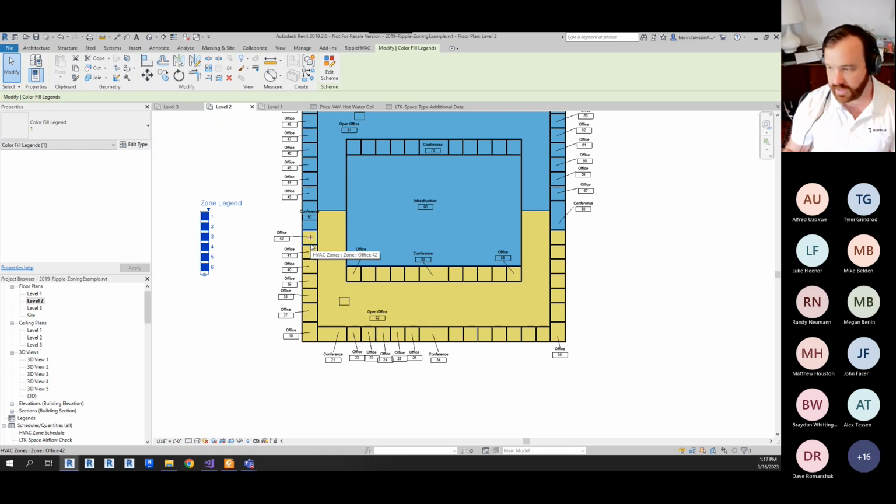So ideally, everything on the same VAV zone has an identical load profile. Throughout the day, it's getting hit exactly by the same sun. It's got the exact same people using the exact same lights, the exact same computers. Functionally, that just never happens. So somebody is always on vacation and they've got the thermostat and the person next to them is uncomfortable. So it's always going to be a trade-off between cost and comfort.